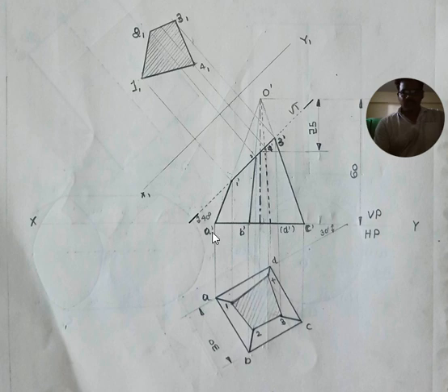Let's say, for example, 1 dash, which is on the OA slanting edge. From 1 dash, we have to draw a vertical projection line until meeting the top view OA slanting edge, and then mark it as 1. Similarly, we have to draw vertical projection lines from 2 dash, 3 dash, 4 dash. Mark those intersecting points, meeting points on the respective slanting edges. Then you connect all those corners 1, 2, 3, 4. The area within that represents the sectioned portion in the top view. Since it is a sectioned portion, it has to be represented by hatching lines. Generally, hatching lines are thin lines, keeping 2 to 3 mm space between lines at 45 degree inclination.